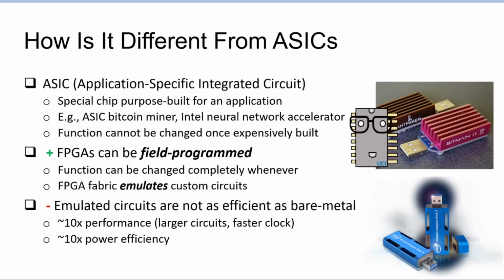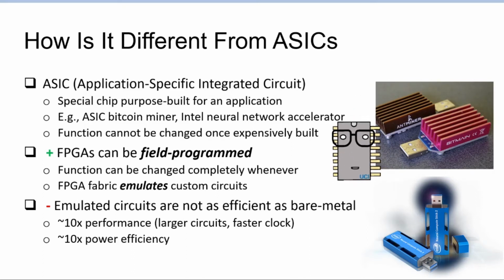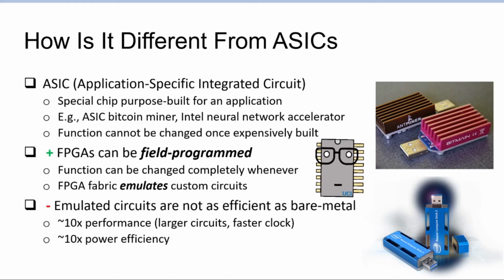The thing with ASICs is that once you expend the effort to design your circuits, to debug your circuits, verify your circuits, and then send it off to production, and then you get your physical chips back. Not only is that a relatively costly process, once you get it back, the circuits that you designed and fabricated on your chips cannot be changed after you get these physical chips back from the factory. The benefit of FPGAs is that they can be field programmed, meaning once you have the board,